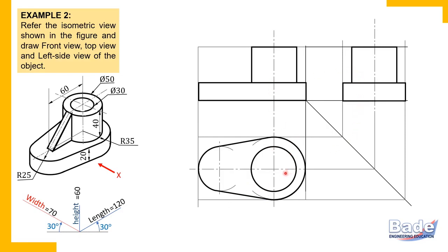Check, up till now we have completed two parts of the object, base plate and cylinder. In a view shape circle, the remaining two views are rectangles. That is the simple logic. Okay. Now this cylinder has a hole. It is a circular hole. Its opening circle appears in the top view. So draw that. Diameter 30 means radius 15. So use a radius of 15 millimeters and complete the circle. It is a coaxial hole, that is, the axis of the hole and the axis of the cylinder are the same. So use the same radius and complete the circle.